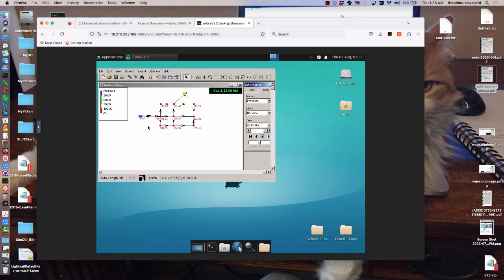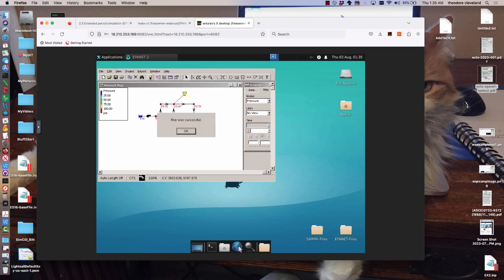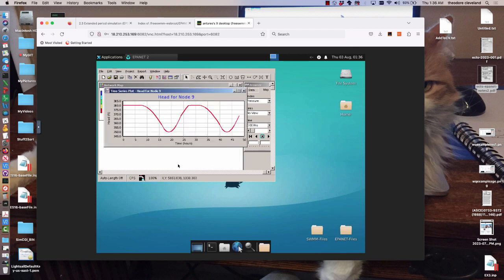Yeah, the pressure's all pretty high. So running the pump at 1.5, the design speed is probably more than necessary. Let's go to 1.25. Because we want the tank to actually drain and fill, otherwise there's no point in having a tank in the system. Okay, that's better.